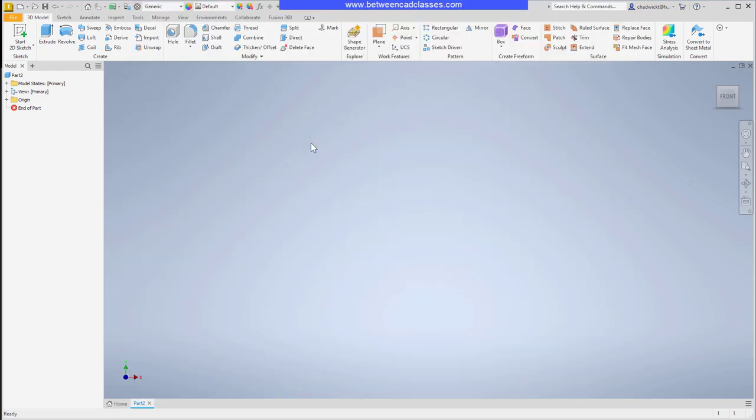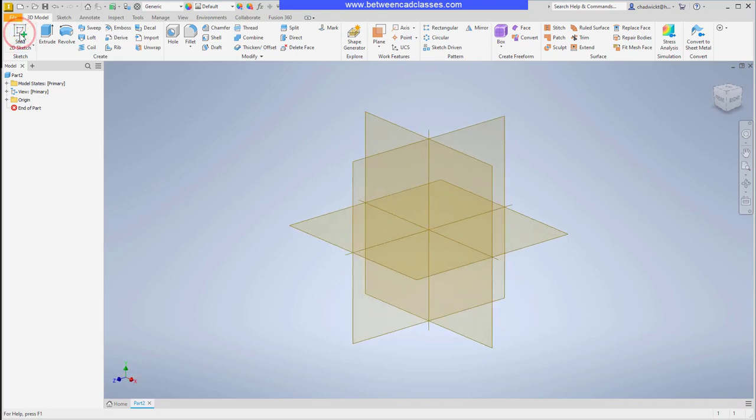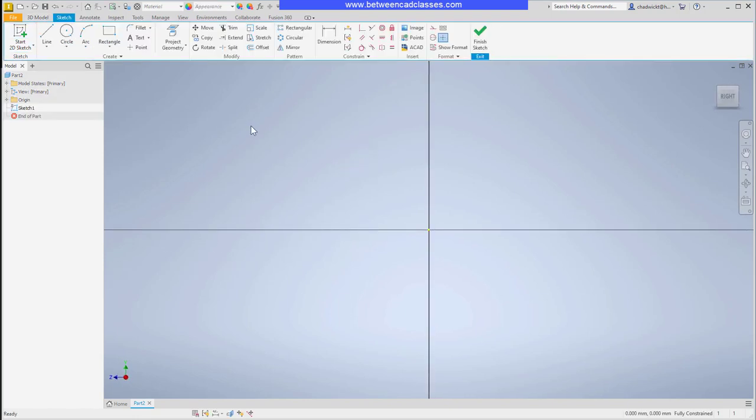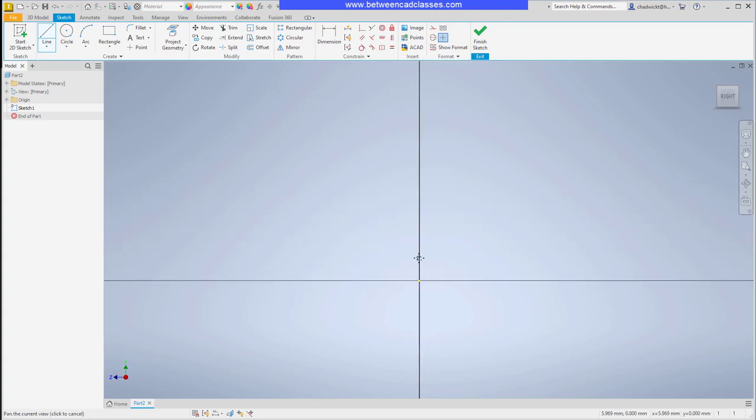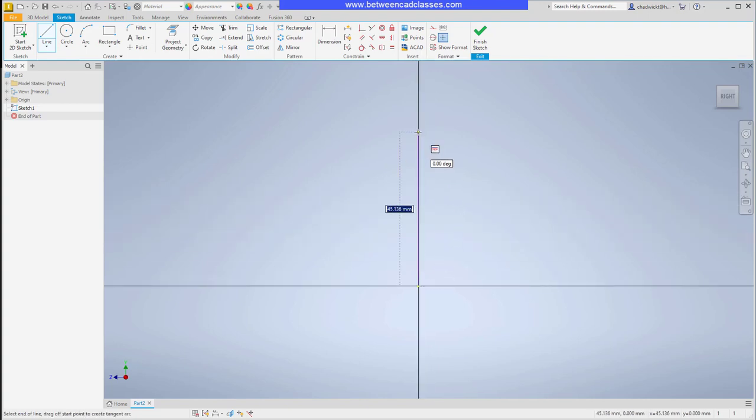So back in Inventor, I'm going to start my 2D sketch, and I'm going to sketch on the side plane here, the YZ plane. Then I will begin sketching my shape. So I'll begin by starting at my origin point here, and you can certainly draw accurately to begin with. I personally prefer to just kind of draw in the neighborhood and then come back with my dimensional constraints here. So I'll create my backwards L shape here.